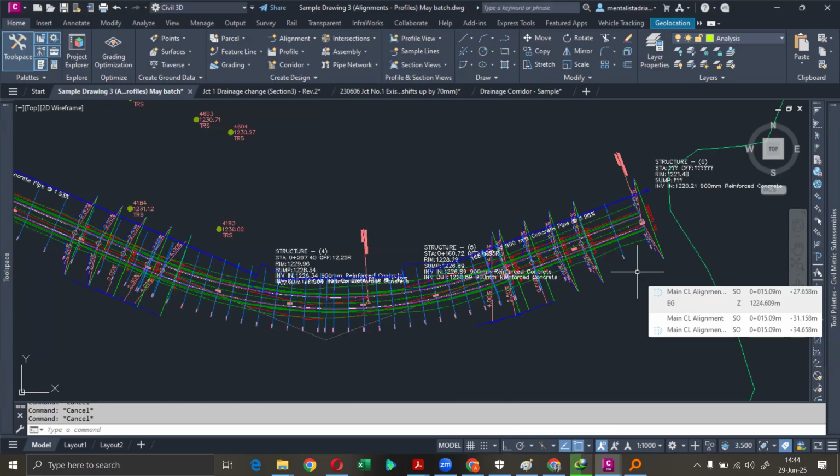You see, here it can look hard, but they tell you to implement on ground, and if you have stations that are more than 20 meters apart, you're going to have errors. You get it? So even when the surveyors are putting points, if you are the engineer, you even tell them to put 5 meters. Unless the section is really straight, you can put maybe 20.